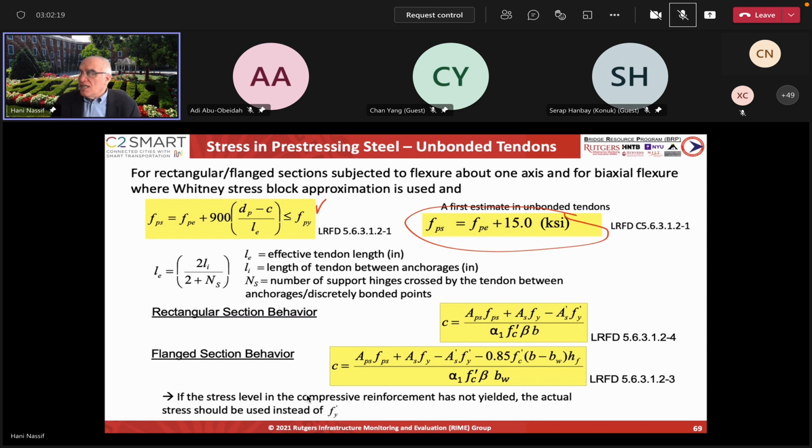Whereas in unbonded, the previous equations, or some codes that have this kind of equations, are very conservative. And that's a penalty on unbonded tendon. So when you are trying to design an unbonded section, the capacity will be less than a bonded, and therefore you go with a bonded. Because a lot of tests have shown that these equations are very conservative, AASHTO really recognized that, and they've tried to address it by doing some improvement, and more or less this one gives a good prediction compared to the ACI code equation.